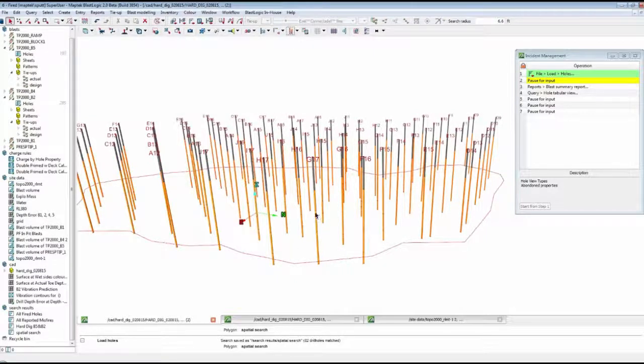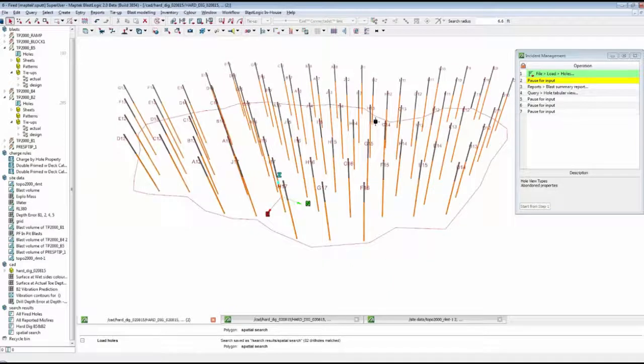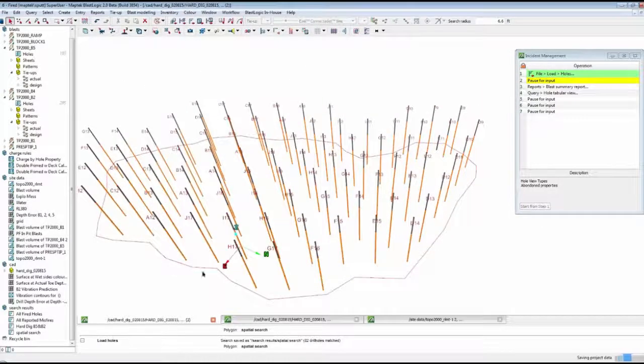So here we're looking at just our explosives design. And quickly a question should come up: I mentioned that the orange is actually ANFO, so why have we loaded ANFO into holes that we know had water in them? That'd be a question for the engineer, and maybe there was some sort of time crunch where the design actually didn't go out properly. So those are just the views that we can look at quickly. We can already tell, without doing much work, that this whole region on the right here definitely had some issues.